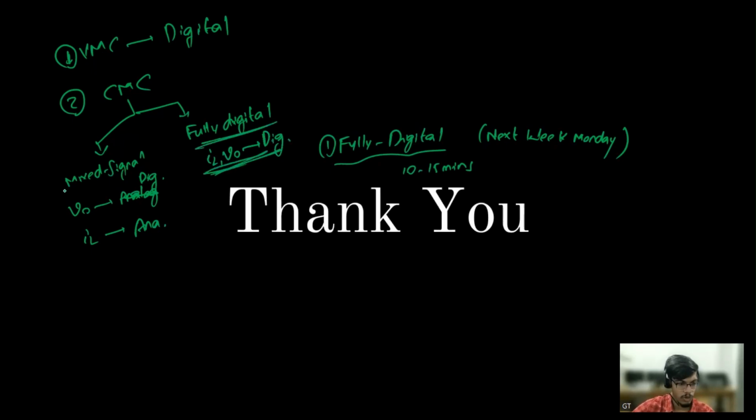But you may ask me, should I go to mixed signal or fully digital? Mixed signal is easier compared to fully digital, because in fully digital we are sampling both IL and V0 and we are emulating, which will pose many stability issues compared to mixed signal. So you may ask me, sir, why are we going for fully digital? Why not mixed signal? This also has advantages because we are sensing IL. We can use plenty of architectures inside the algorithm, and I can implement complex algorithms in Verilog code, and I can use IL.